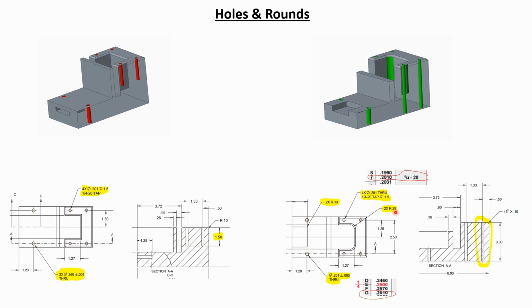The addition of the 0.28 radius will all of a sudden allow the use of a good size end mill operation to machine out the pocket. The original design has sharp internal corners that might have required a ram EDM operation to attain, and that is an extra expense and also extra setups.